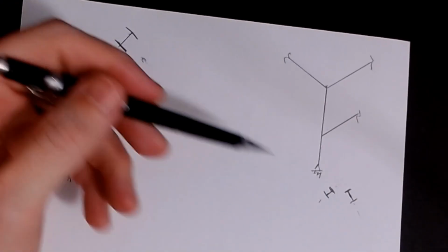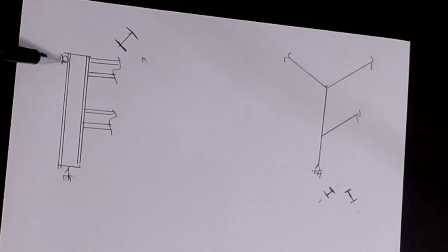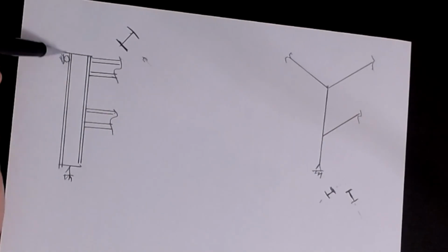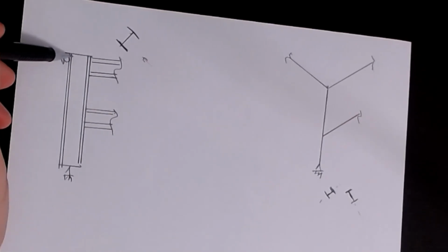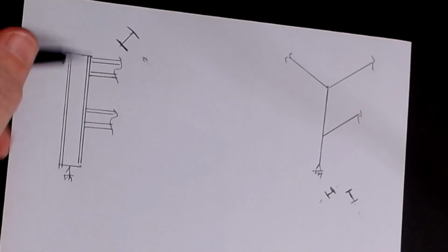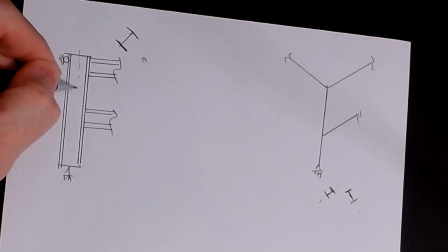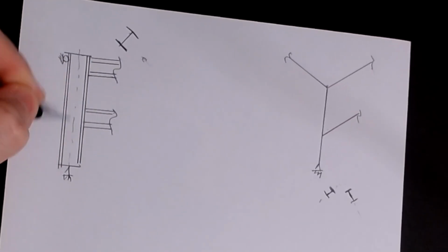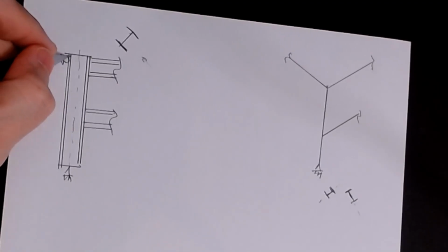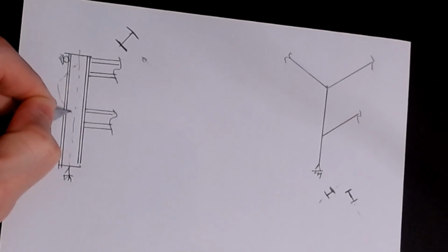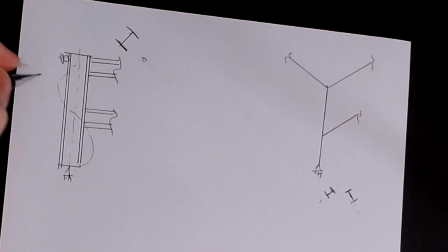In reality, it probably is, and we'll have to talk about that in the next video. What do I do when that's not the case? Remember, our assumption so far is that our K-factors are based off of a column that is restrained at the top and the bottom and is free to do whatever. Well, we know that in this column, for it to buckle in this plane, if this is my center line, you would see something like this, where I would get a bow this way, and then I would build an S shape this way.